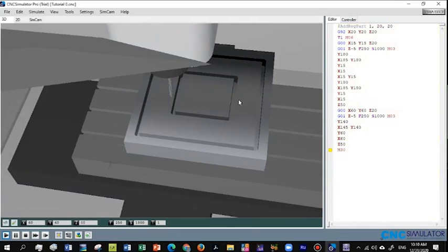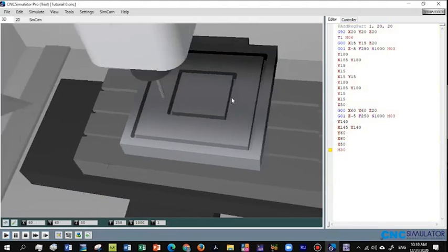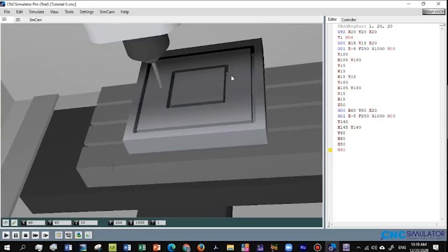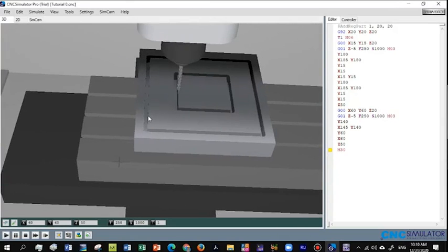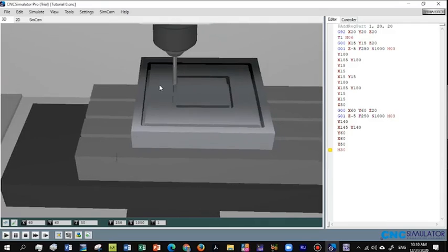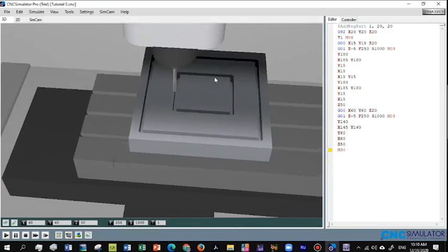So this is for the linear profiling. If you want to create any type of linear profiling, you need to define the coordinates and define the line or the path for the tool to go through in order to create it. You can change the dimension here. When you change the coordinates, you change the path for this tool to make the milling for the machine.